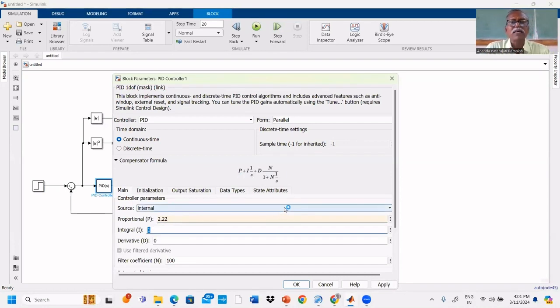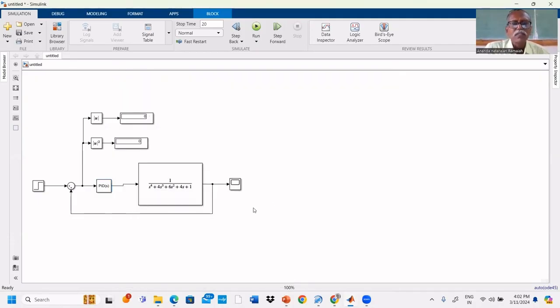And here you have to see the formula. In PID, everything is in the numerator, that's why we can substitute 0. Sometimes if it is Kc by Ti, you should not enter Ti equal to 0. So here we can enter 0 because it is I only. D also we can enter 0. That's all. So we entered the P only controller. Now we can simulate for servo response. If you give step input,